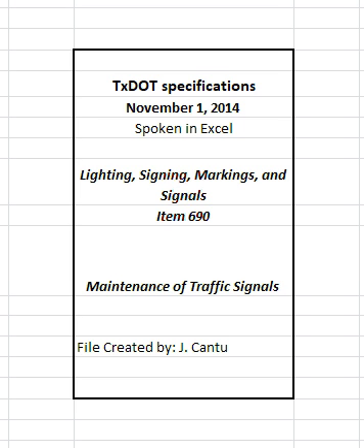Install a separate cable from the breaker load panel to each luminaire. 4.11 Signal head assembly. Install, repair, replace, remove, or modify pedestrian signal heads or vehicle signal head assemblies in accordance with item 682, vehicle and pedestrian signal heads, as shown on the plans, or as directed.